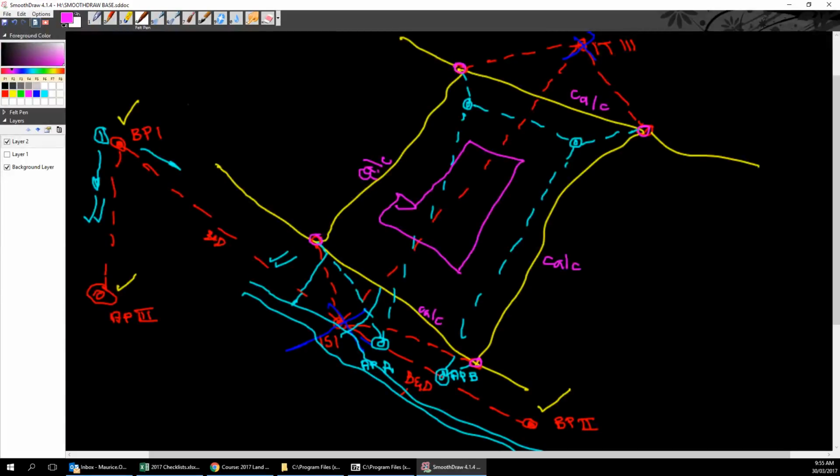Okay, so straight away we can see that we're now not able to see down this line here, but if we wish, we can set up now on this mark here. Let's say we can set up there, and we can check down there to make sure that we're in agreement there, and we can check down here to make sure we're in agreement here because we know exactly where we are on the lot, and then we can calculate into these boundary corners of our house.